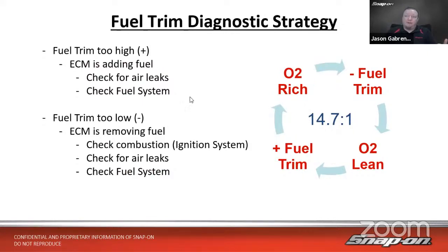Okay, so as a diagnostic strategy, how do we want to approach this if we see some issues with our fuel trim? If the fuel trim's too high, once again, that means the ECM is adding fuel, so it's putting too much fuel in. So we want to check for something that's giving us too much air. So air leaks, maybe a vacuum leak. Check the fuel system, make sure it's got enough pressure, enough volume to get in there. We'll talk about volume in a second.